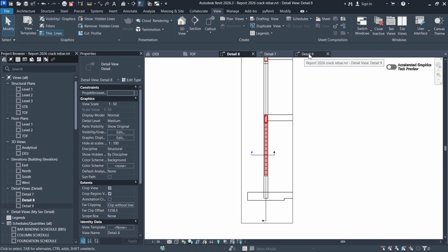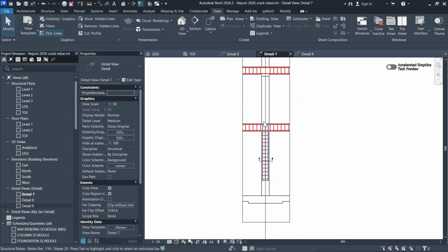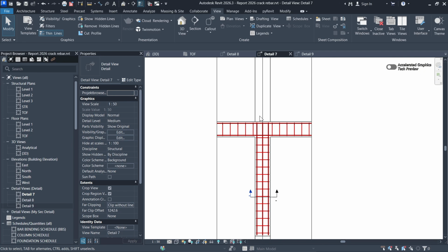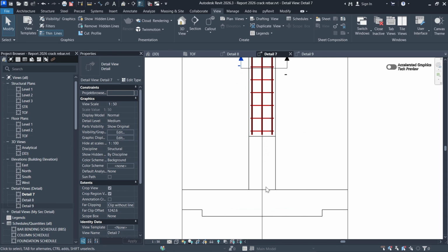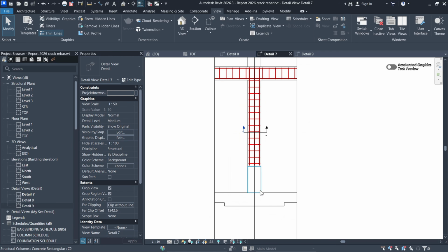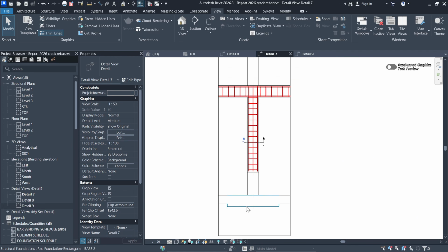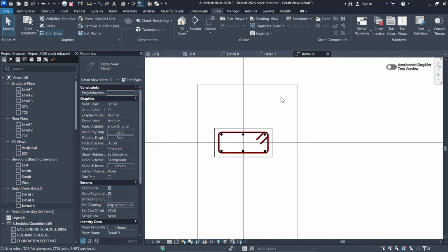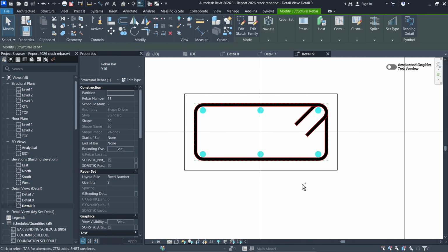Now before I start copying or propagating, I just want to ensure that these bars are sticking out. Okay, maybe by 700 or so, I'll start the bars. Okay, now if I want, I can also propagate here, but sometimes when you try to propagate down here, because the conditions are different, they do not behave well. So let me start by selecting these, and maybe I can even use this one here. I'll select these bars, hold Control and select the bars.